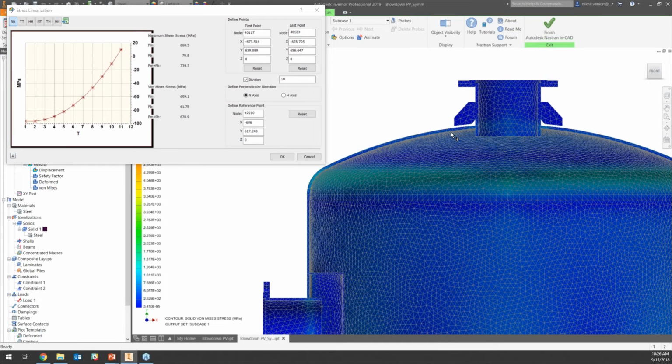And secondly, the way membrane stresses on a shell element are calculated is very different than membrane stresses extrapolated from solid element results. So you will see some difference in results, and again, that's not really an apples to apples comparison with the pressure code. The entire idea behind this is to make sure that you have that apples to apples comparison.